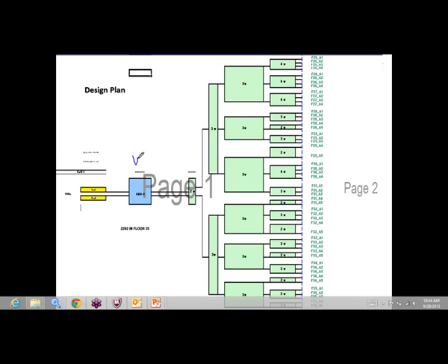let's say this is 43 dBm from here, 3 dB of loss in the CDU. So I got 40 over here. So I'm at 40 dBm over here. So 40 dBm will be split. So it will be on this line and this line. Can somebody tell me what will be the power after the two-way splitting? What will be over here? And what will be the power on this line? Can somebody tell me? Yes.